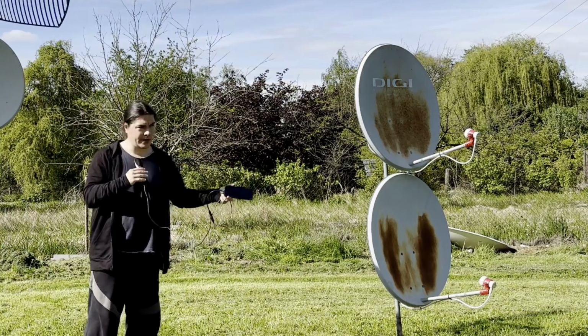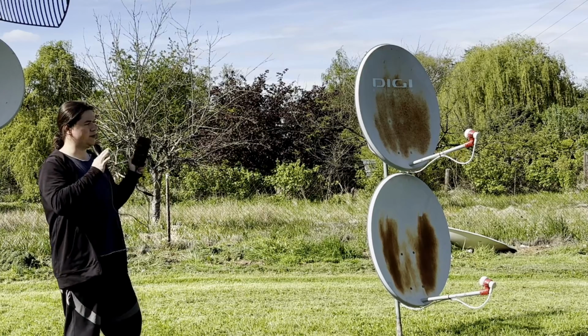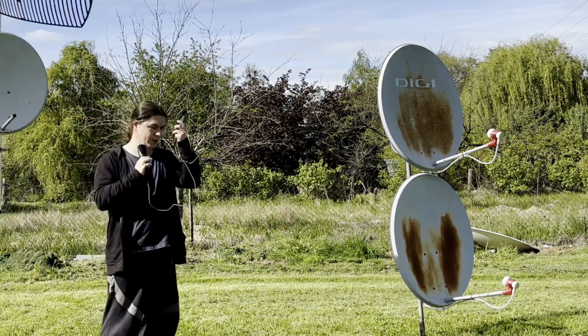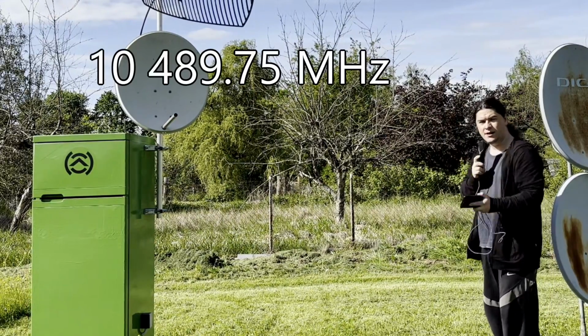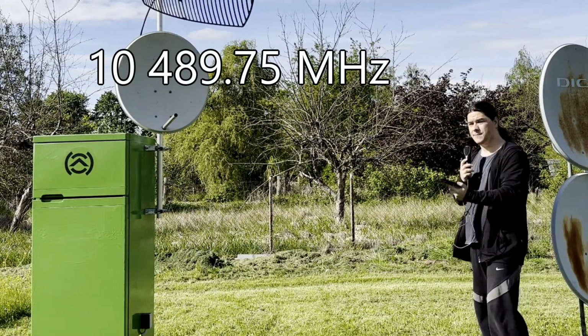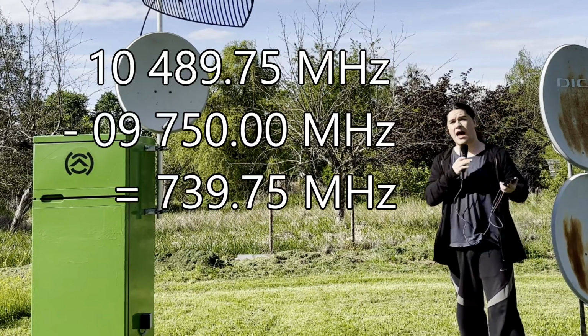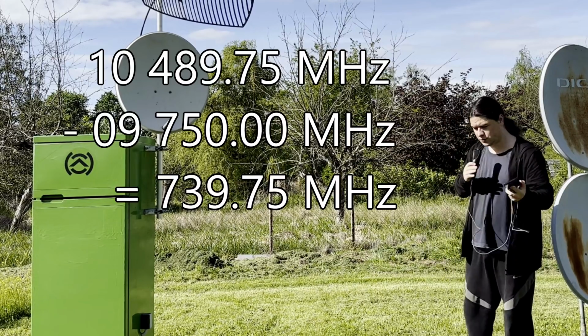Once you have the LNB powered up, you have to calculate the frequency where QO-100, the narrowband transponder, is being down converted to. The center frequency of the QO-100 narrowband transponder is this. Then you have to subtract the local oscillator frequency of your LNB. In my case, it's 9.75 gigahertz, and you get the resulting IF, or intermediary frequency, which is where your SDR wants to be listening.